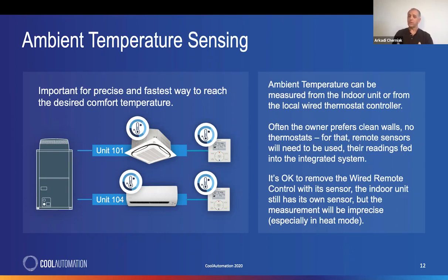The old style systems, the traditional systems, use only the thermostat to measure the temperature in the area where the thermostat sits on the wall. If it's on the back wall, it will measure it over there. If it's in the front, that's where it will measure it. In the case of the newer, advanced systems, it has a set of different sensors spread around the facility, and they can be used or not used depending on how precise you want to measure it.